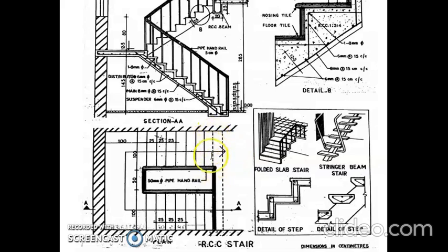Sorry, this point up to this point means the last rise line ends at this beam line, and the remaining extends a slab portion so that the first step is not visible in the plan. It was below the handrail and the slab portion. So this dotted line, also you can say this dotted line as the first step of this first flight.